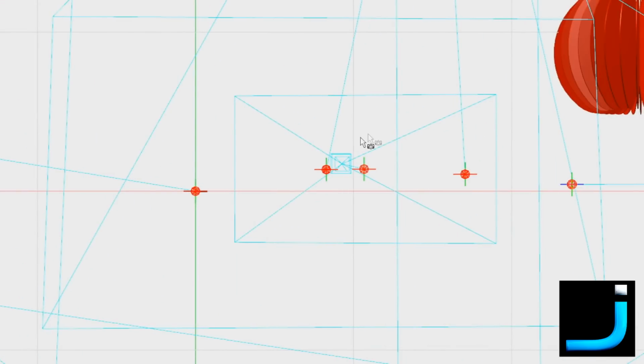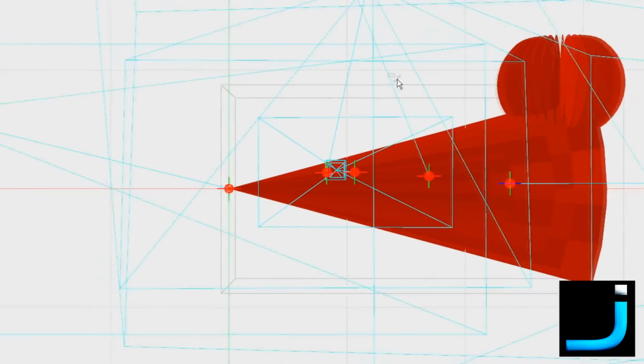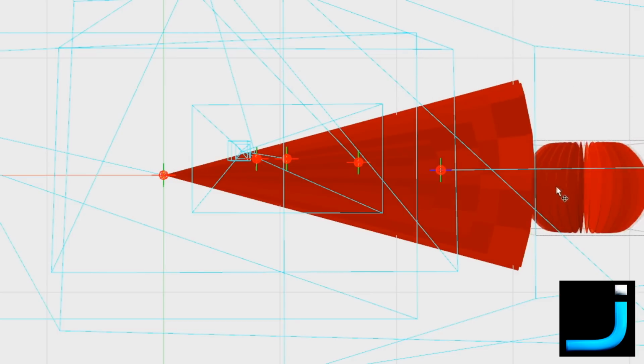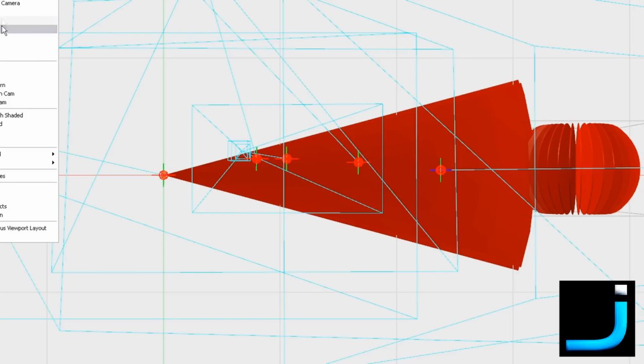Now remember, because it's very high gain, we get an even narrower field of view. Let's turn on the Yagi. Bang. You can see this is only about 30 degrees field of view here. So this is even more important, that you make sure that this antenna is pointed directly at your plane. And again, this is a linearly polarized antenna, i.e. it's either vertical or horizontal.